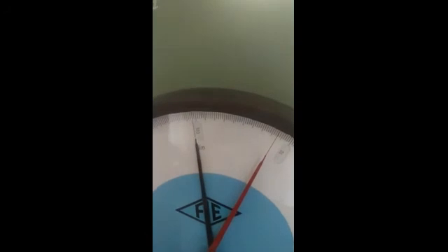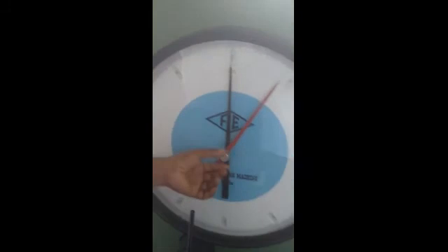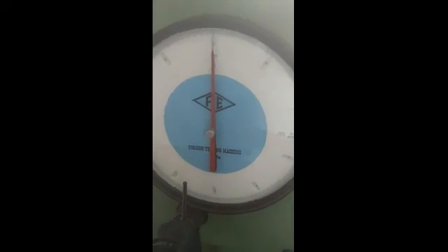Initially we have to set the needle to 0. This needle moves only when the torque is applied. But how do we set it to 0? There is a fine adjustment here. With that we can set the needle to 0. In a similar way, move this one and place it here, touching the black needle. And here, where the degree is, we also have to set the initial reading to 0 with the reference pointer.